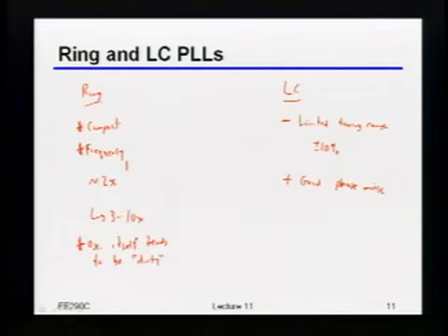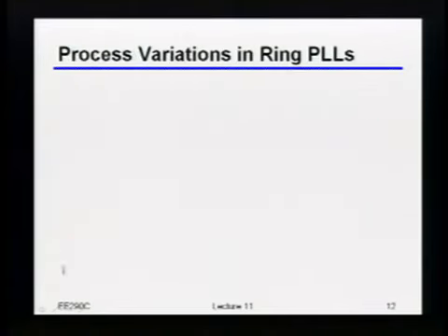We'll get into this in a lot more detail next, but if the ring oscillator tends to be pretty dirty, that tends to mean that you really want as high a bandwidth as you can in your PLL loop, right? Because the higher the bandwidth of the PLL, the more it'll reject the noise coming from that ring oscillator.